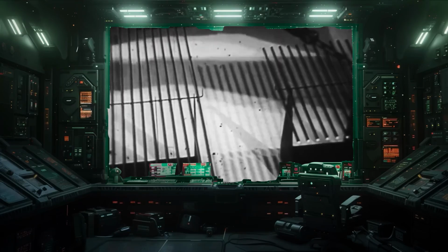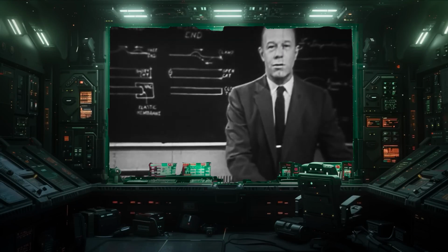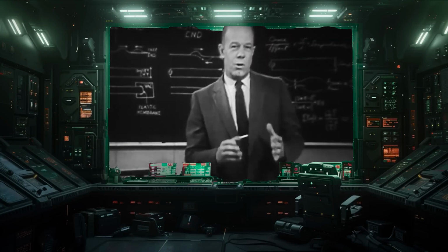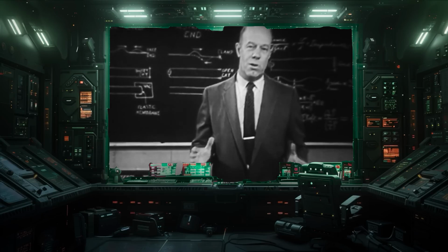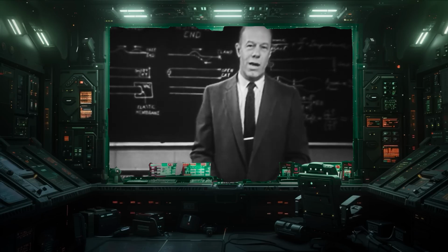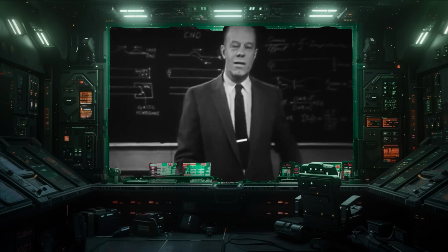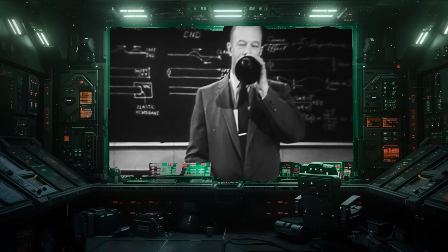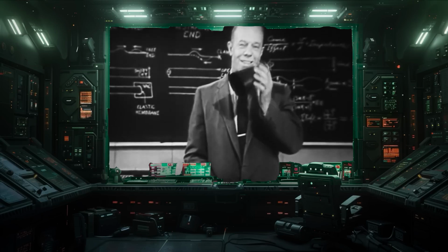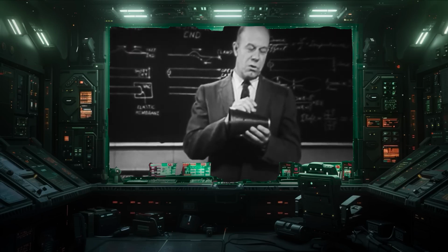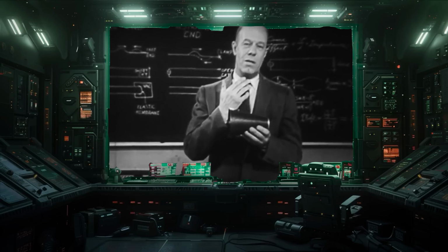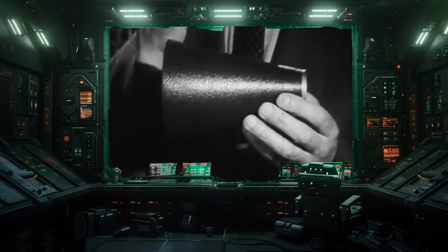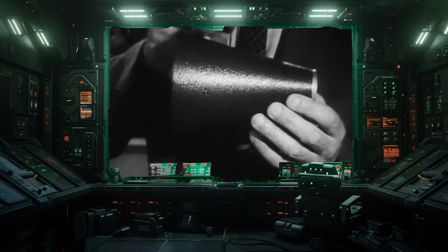For applications in acoustics, mechanics, shortwave radio, and the like, where it is desired to accommodate much broader ranges of frequency, we have a different kind of matching transformer, to which this megaphone is a first approximation. Now, the megaphone smooths over the impedance discontinuity between the air column in my throat and mouth and the free air in the space around me by means of a gradual taper.